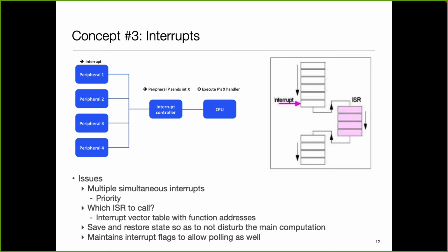You also need to become familiar with how the processor is handling interrupts. Processors differ, but very commonly processors may have more than one type of interrupt, high priority, low priority, or multiple levels of priority. So being familiar with those things is often very helpful, although typical things like Arduino abstract it all away.